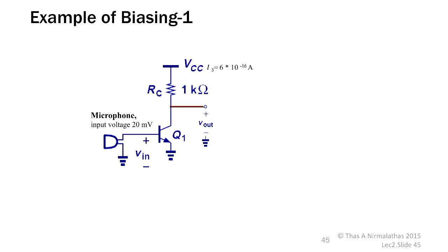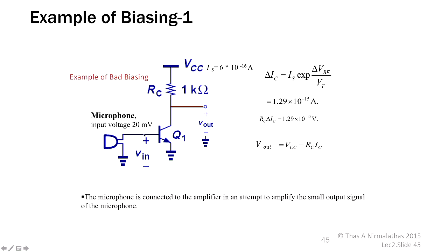Obviously, in this circuit we don't have any biasing actually. The forward biasing is absent here, so you don't get any amplification, which we already did. So we need to make sure that we have proper biasing here between base and the emitter. So we can't connect a microphone here. Then we need some voltage here, VB, the voltage between base and the emitter.